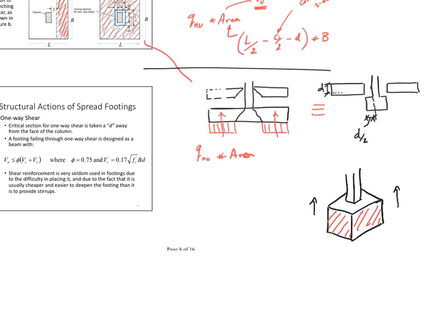I simply calculate this parameter, the blue line, which is the same as the blue line here. I calculate this blue line and then I multiply it by d. So that blue line over here is b node, the parameter, and that depth here is d. That's why in all the shear capacity calculations for punching, you will see b node times d. What is this? It's the area where you broke at. So the more you have d, the better capacity. The more you have b node, the more you have capacity.